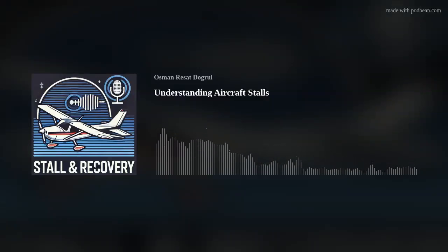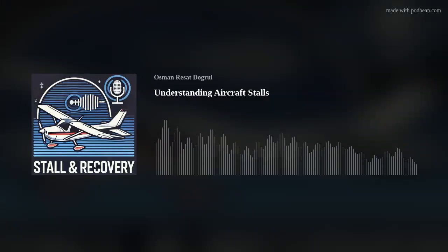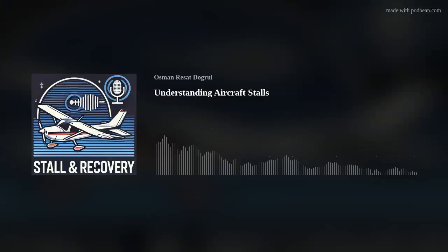What is superstall? A superstall, or deep stall, is a condition where an aircraft becomes unrecoverable from the stall. This occurs primarily in high T-tail, rear-engine aircraft, where the stalled wing creates an increasing nose-up pitch tendency. The most infamous example was the 1972 British Airways Trident crash in Slough, England.